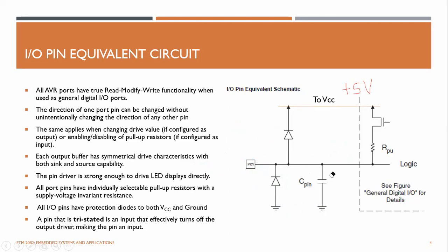And there is some capacitance here, parasitic capacitance. That is not what they have put, but it is due to the nature of the microcontroller. You can't avoid it. It is in the picofarad range. Sometimes it needs troubleshooting when you're driving very high frequency digital signals. Then the effect of this capacitor will be critical. Other than that, there's nothing to worry about with these capacitors.